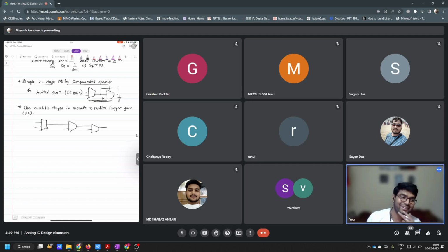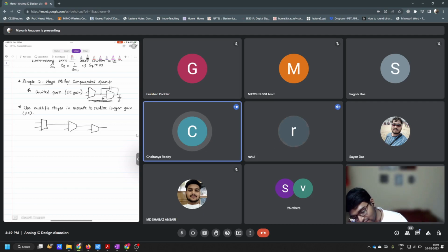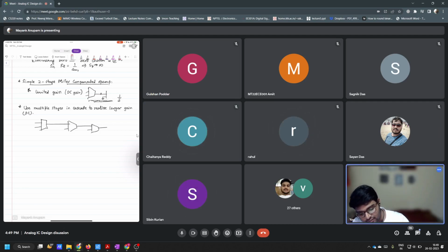And why is that required? For stability, we will have a proper phase margin. Correct. If we do not add this capacitor here, what will happen? From input to the output we have two delays. This will also have some parasitic capacitance here. So the first delay element will be this capacitor, and then again we have a delay due to this capacitor. These two delay elements add two poles, and delay in the circuit is simply not good. It will add instability to the system.